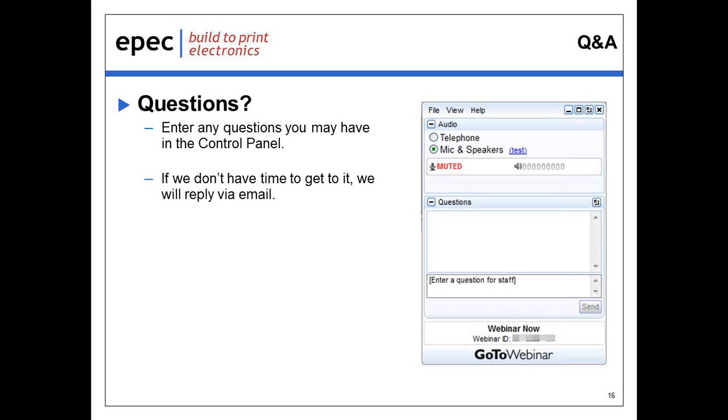Another question has come in. You've explained that cables are shielded to eliminate noise. Are connectors shielded as well? And the answer to that question is yes, within reason. There are shielded connectors that are available. And when we do a connector process, if we know that the signal is going to be a high-speed signal, we will also wrap the back of the connector with a copper foil and solder the edges to make a complete EMI RFI protected circuit from one connector down the cable to the other end as well.